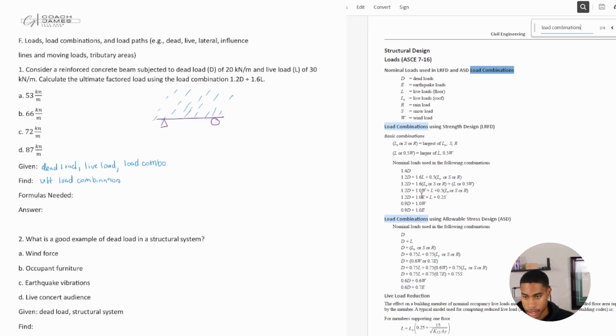In this particular formula, it would be 1.2. So you've got some dead load, and dead load could be the weight of the beam, or the asphalt that's coming across, maybe a bridge, just stuff that's going to be there that's not going anywhere. That's there pretty much until you remove the whole structure. Then you've got live load, so you could have people walking.